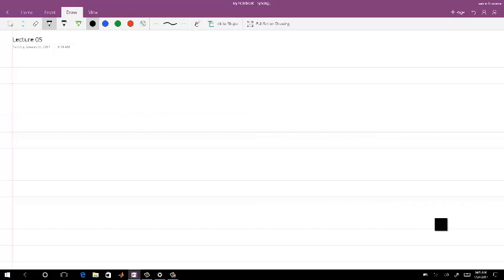we have seen the frequency acquisition in type 1 PLL and type 2 PLL, and both these frequency acquisitions we see in context with the sinusoidal phase error detector. Now there exist many other phase error detectors, and since this is the first block which detects the phase error between the input and the output clock, we will look at different kinds of phase error detectors today.